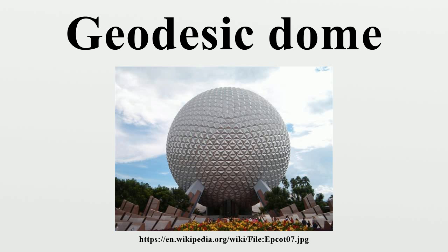Each triangular face of the icosahedron is subdivided into n² similar triangular tiles, n being the chosen degree of subdivision. The small triangle's vertices are then projected onto the sphere, carrying the arrangement of edges along with them. When fitted exactly, the sub-triangle edge lengths assume different values, which thus requires links of many sizes to form the structure.